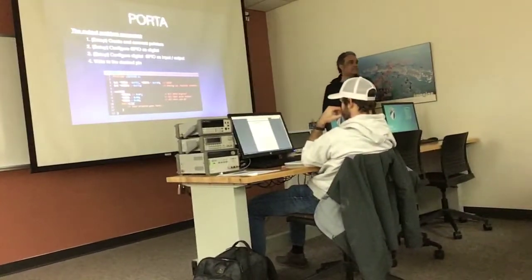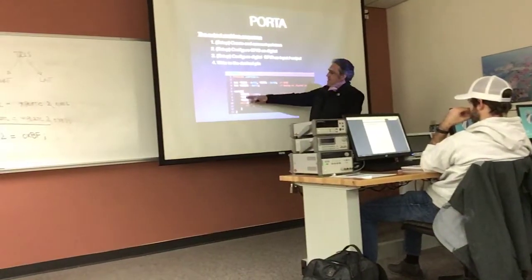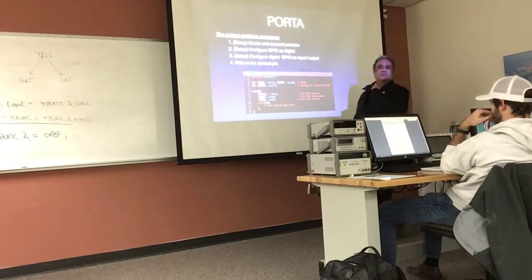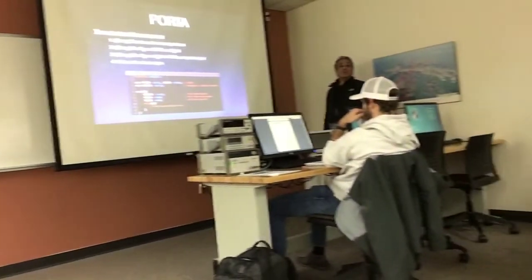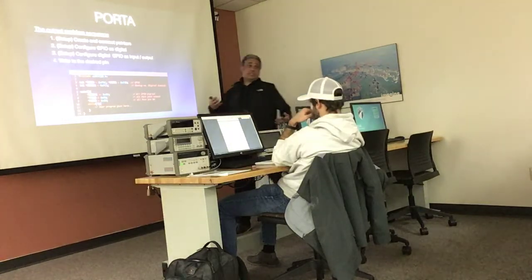See the sequence? I actually make it a digital bit, then I make it an output, then I write voltages in it. So that's the sequence that you have to follow. See that? If you're going to do a digital input, same thing.